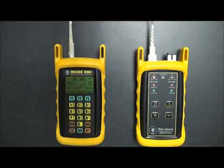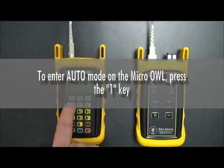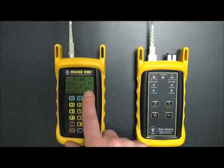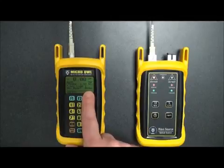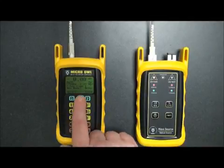So to enter auto mode, in fact, both units need to be in auto mode. Now on the micro owl, to enter auto mode, simply press the 1 key, A for auto. So press 1, you'll see it says auto on, and then you'll see that down here where it says wavelength, it's toggling between the current wavelength and auto. Now when it's toggling this way, it means that the micro owl is waiting for an auto testing signal from the light source.